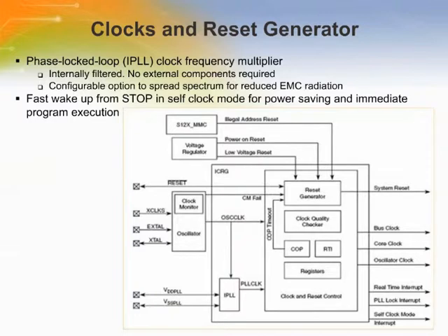The clock generator creates the clocks used by the microcontroller. The individual clocks are gated by conditions of different modes, such as stop and wait, and by setting respective configuration bits. The peripheral modules use bus clock. Some peripheral modules also use oscillator clock.